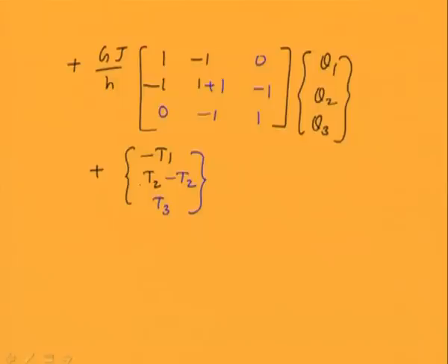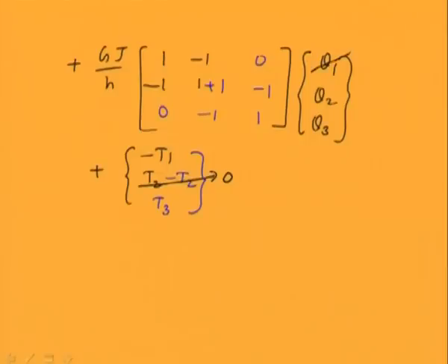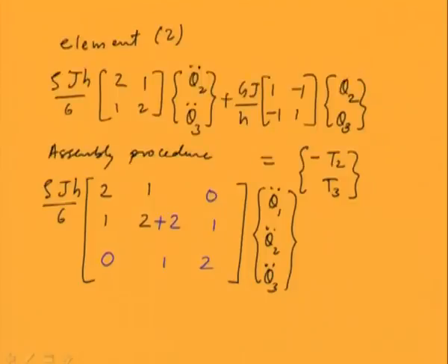So here you can see that this term is getting 0, because here one end of the beam is fixed, that means at node 1 it is fixed. So there the displacement will be 0, and the other end of the beam, which is the free end, that is a cantilever, so the torque will be 0. So those boundary conditions will be applied in this. So this becomes 0, then T3 is 0 because that is a free end, and in the previous slide theta 1 is 0, that is the mass matrix.